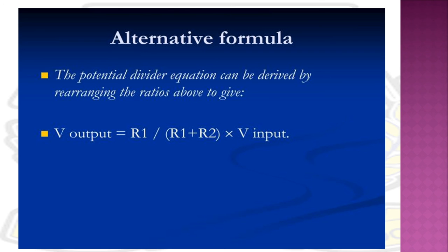Resistor voltage dividers are commonly used to create a reference voltage or to reduce the magnitude of a voltage so it can be measured, and may also be used with signals at low frequencies. Students, for direct current and relatively low frequencies, a voltage divider may be sufficiently accurate if made only of resistors.